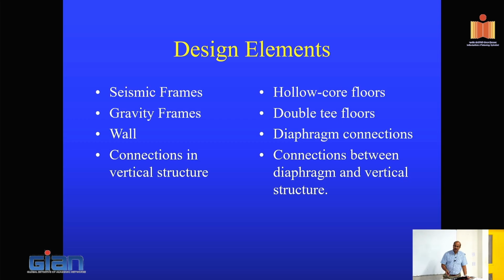So from a design point of view, I want you to just get a feel for these things. So we have a seismic frame, we have gravity frame, wall, connections in vertical structure. You have hollow core floors that need to be connected. You have double T. So you can see how you make the structure more complicated, but the advantage is that in one structure you can test all of these details.